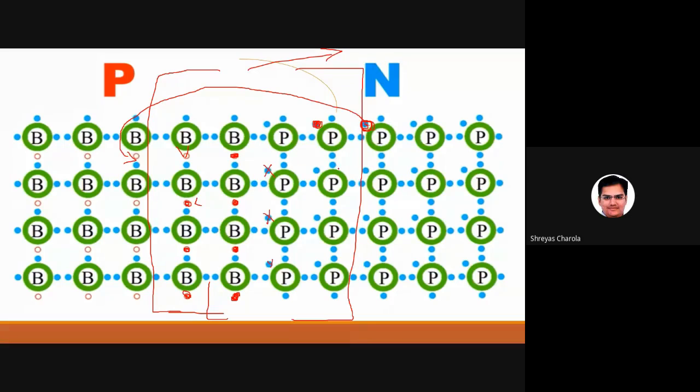Okay. So when you don't apply any voltage and you combine these two materials together, it will create one junction, and that will be a permanent junction. After that, no more junction will be created. And if you want to expand the junction, you need to apply a certain voltage from outside. Outside source means a battery you need to connect, so that these electrons will get extra voltage to break this region and then come and join over here. Is it clear, all of you? But if you don't apply any external voltage, what happens? The junction will remain the same. This junction will stay as it is.